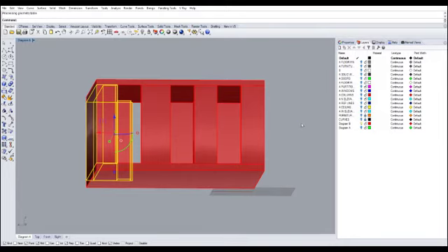But before it has the combination of both, remember what we did with the white diagram? We had to assign the white base, right? So we're going to do that too. We're going to assign a color base to our other color diagram Toon Shaders. So let's do that. Color diagram 1, let's change it to color base 1. Color diagram 2, let's change that to color base 2. And last but not least, color diagram 3, color base 3. So now we have 4 separate sets of Toon shader called color diagram 1, 2, 3, and white diagram.